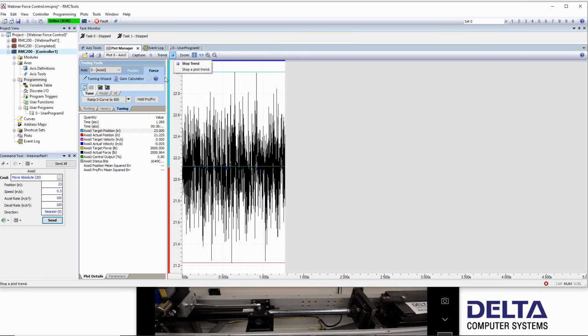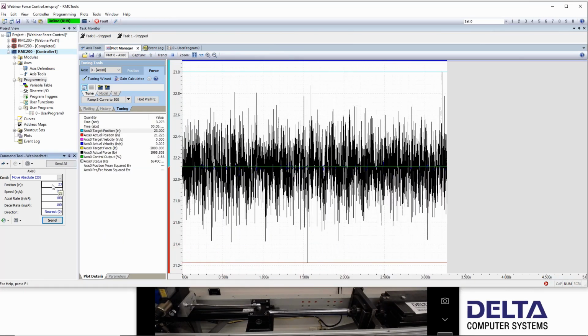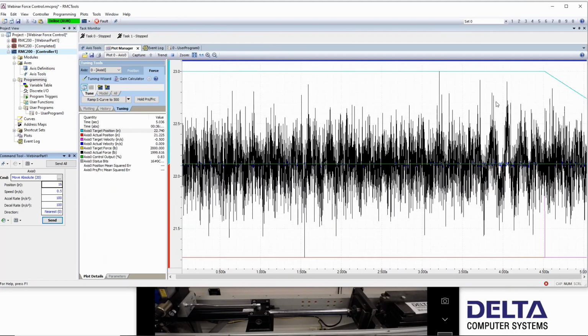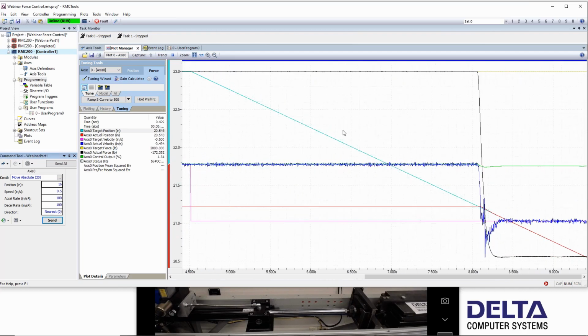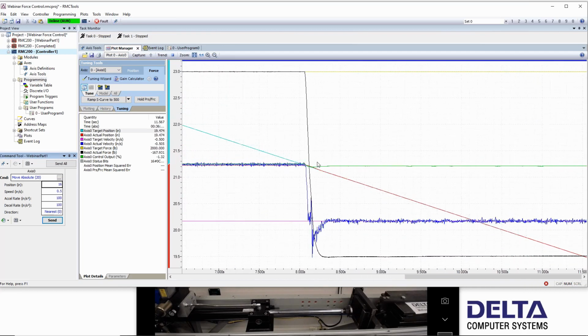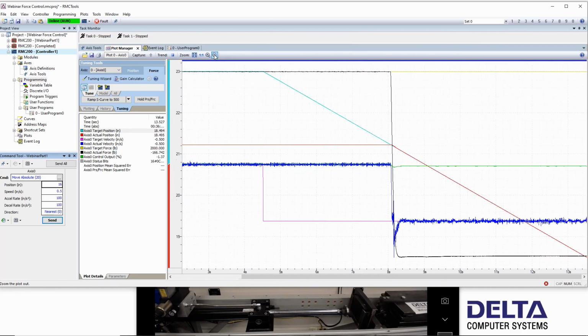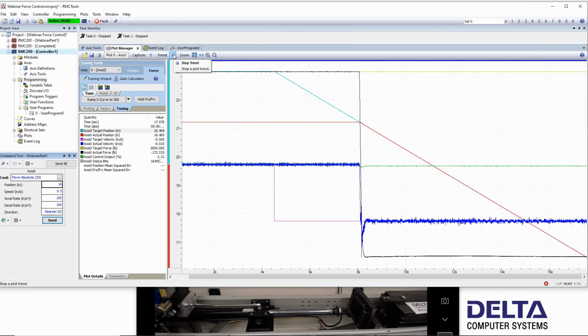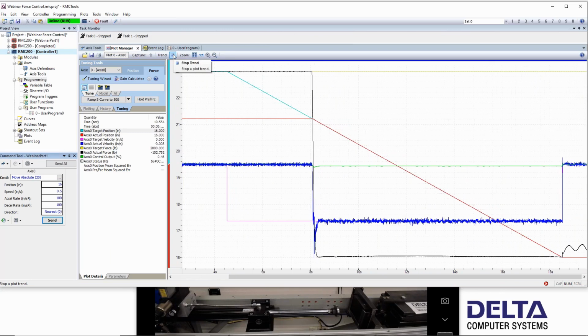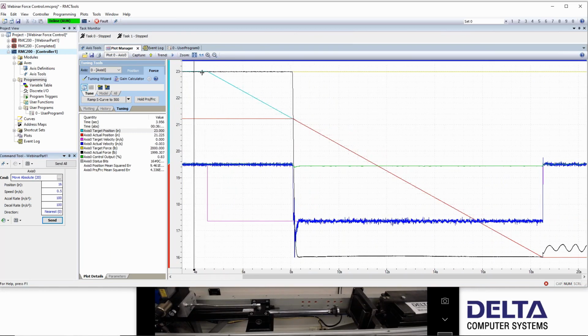And if I start a trend again and then move back to 16, we should see the target force starts coming down, and eventually it reaches the actual position, then the actual position follows down, and then we continue back to our motion to whatever position we command it to, 16 here. So we see the target is beyond there waiting for that.